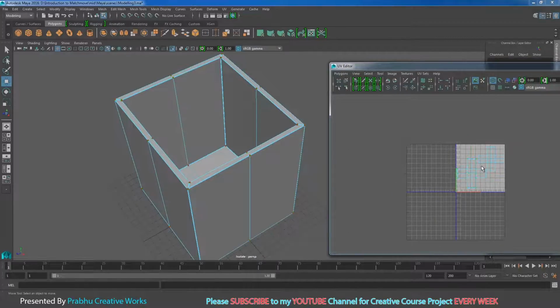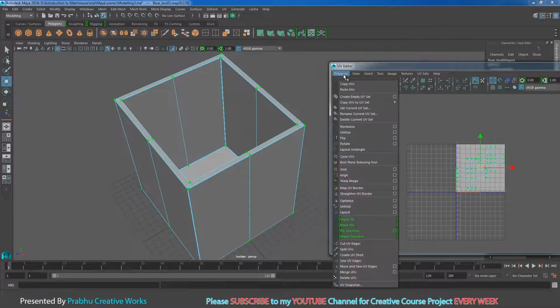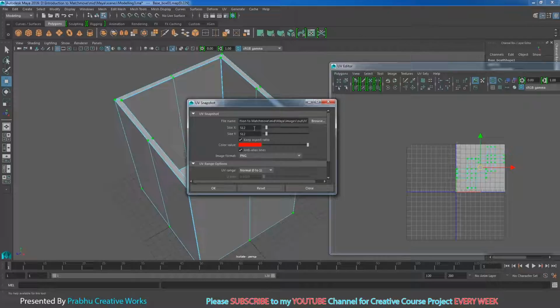So now we want to make the texture in Photoshop. So right click and choose UV. Select the whole UV over here, choose Polygons, and choose UV Snapshot. Now I want to give at least 1024 pixels, because it's a big object.